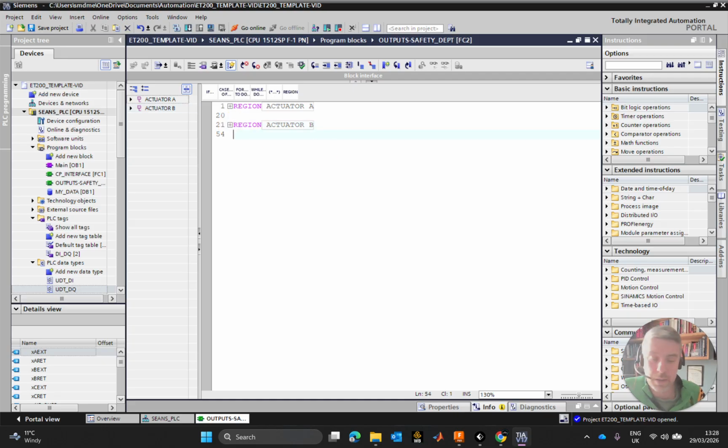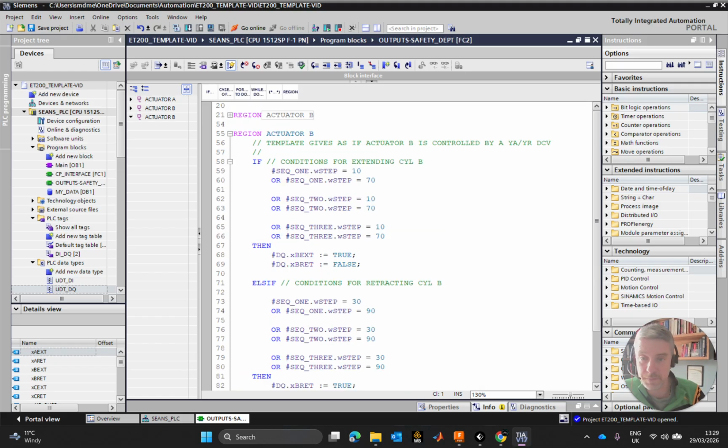Okay, now we can put in actuator C. Now, how do you want to put in an actuator C? Well, what's it typically going to be? The only change to that is that you might have a solenoid actuated spring return to center valve. But if you have a spring return to center valve, you're in a neutral position. It's not going to retract the cylinder that should otherwise be extended. It still will stay extended, so it still will behave as if actuator B behaves. Okay, so just for thoroughness, we'll just throw it in like this then.